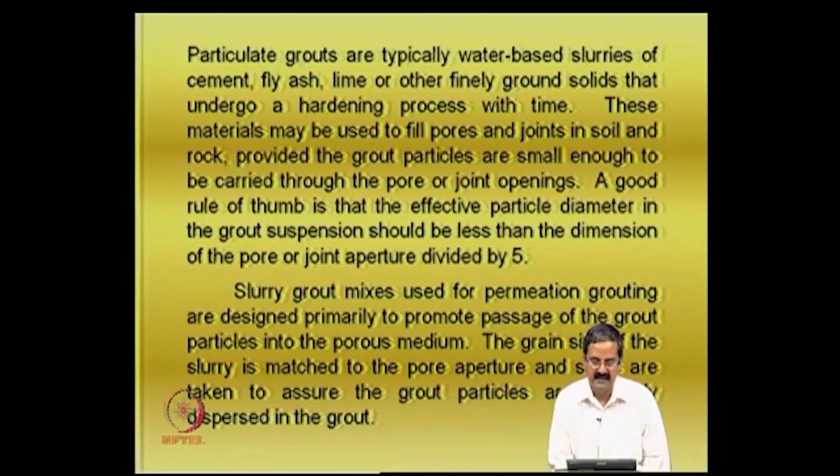The slurry grout mixes used for permeation grouting are designed primarily to promote passage of the grout particles into the porous medium. So, we are trying to really see the grain size of the slurry, and see that it satisfies certain criteria and has a certain relationship with the pore aperture size, so that the grain size will match with the pore size of the existing soil or the rock if there is a joint.